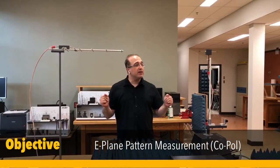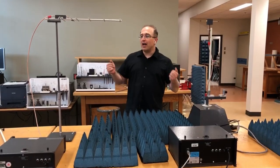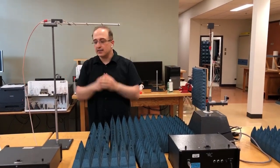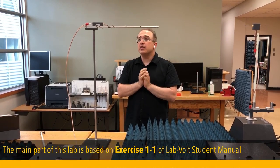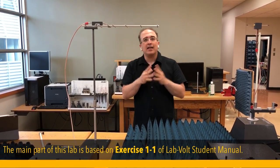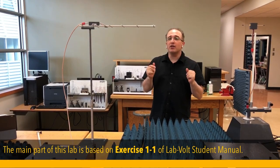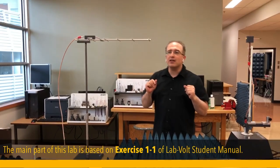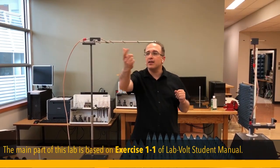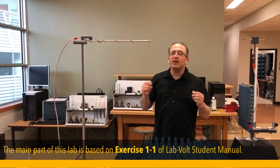Okay, so right now we want to perform the first radiation pattern measurement. So as you see, we have our Vivaldi antenna, our Yagi-Uda antenna fixed here. This Yagi-Uda antenna right now has horizontal polarization. Sometimes it's very difficult to figure out the polarization of the antenna, but for this type of wire antenna, it's relatively straightforward.